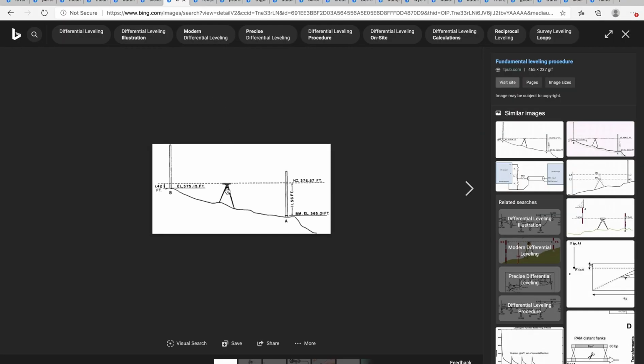So you have your first stadia, your second stadia, your backsight, your foresight. Then you view here the values from the stadia rod. From there, we can now get our elevation. Mathematically, we just compute the elevation using the values that were given or that were cited.